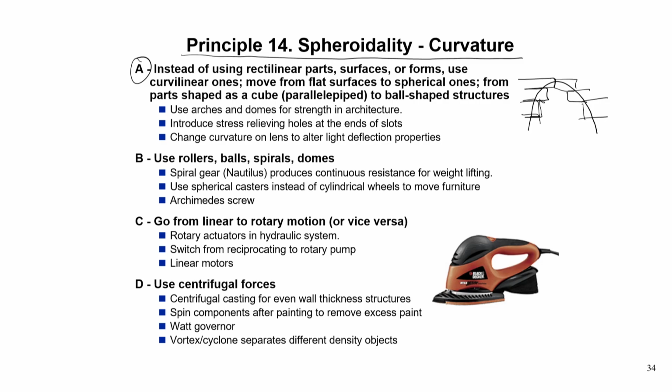And the advantage of going for curvature is that you can then keep the system predominantly compressive in nature, and compressive systems are good as far as stones and bricks are concerned, because they have a higher compressive strength than tensile strength. So, it has been used for making such structures which can predominantly carry compression.